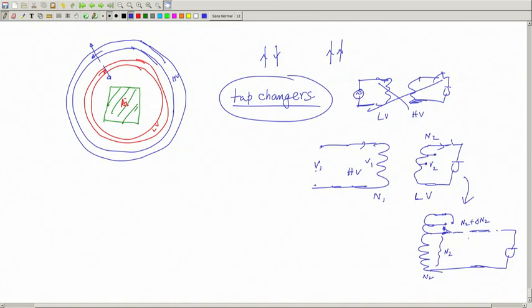That is, it was supplying the load, and you find across the load people are complaining the voltage is small. There is a switch. Those will also be oil immersed, I hope, and you put it there. That is another interesting thing, how tap changers work, but the idea is that you will move it here, and these are called on load tap changers.